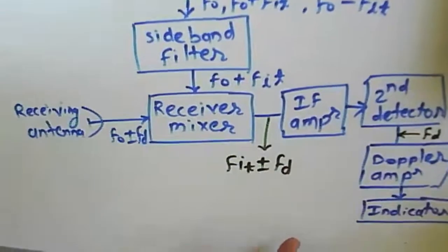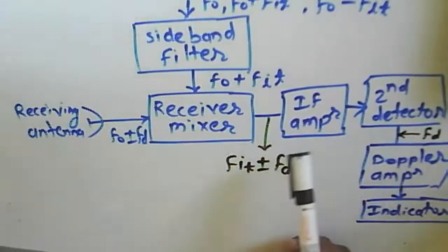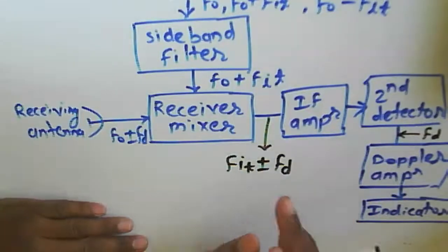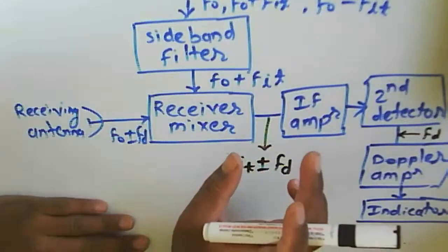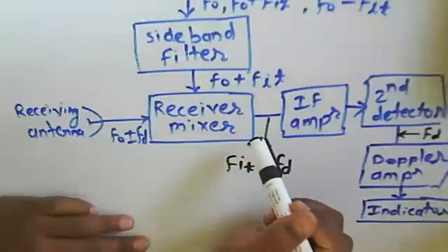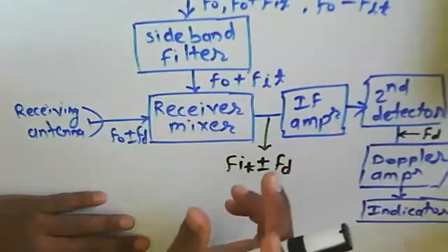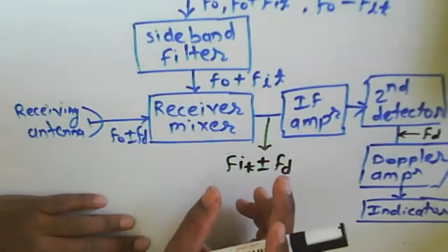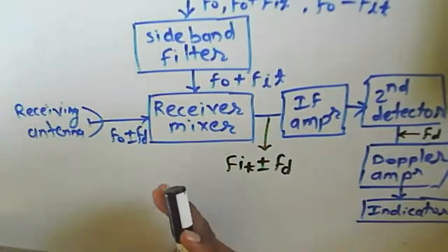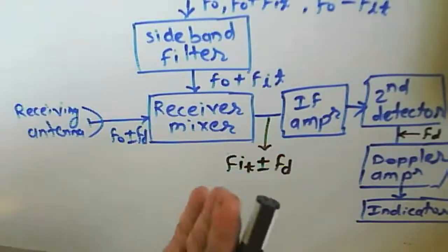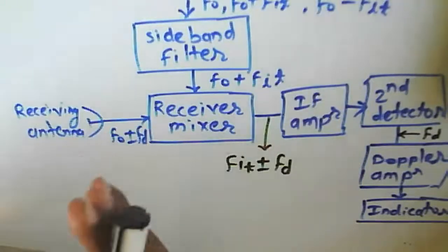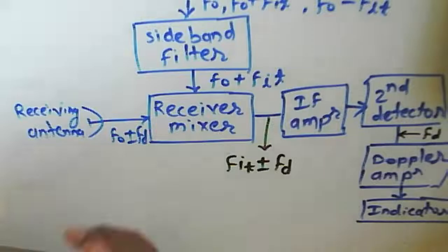And again we are supposed to use a filter, and that filter is to be used only for understanding what the reference signal will be, because a filter selects one of the sidebands as a reference signal. That's why it will improve the sensitivity, because we say f_O plus f_D or f_O minus f_D. So where will the plus or minus sign be?